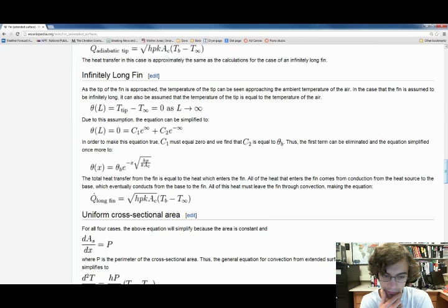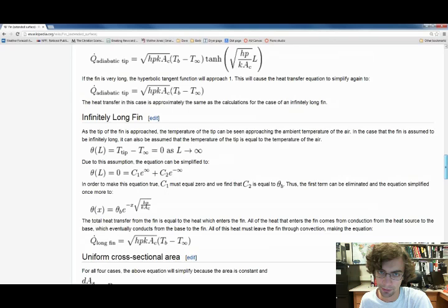So you'd write that heat balance down. So you'll have terms like this second partial derivative of temperature with respect to Z. You'll have the convection term. Be careful of how you specify your areas. I won't go through exactly how to do this.